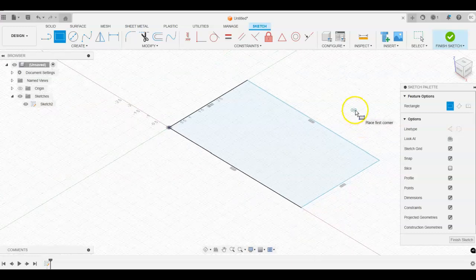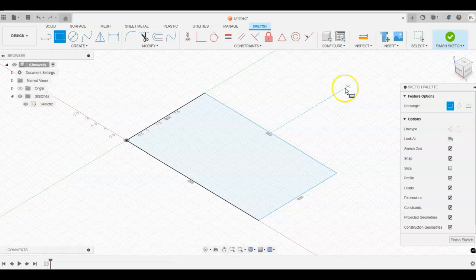right side, left side, bottom, so we can kind of select all the different planes that we could see up here in our view cube. So in this case, I selected the top. Generally, it depends on how I'm approaching these problems, whether I want to sketch on the front plane, the side plane, or the top plane. You'll learn a little bit more as we go through.